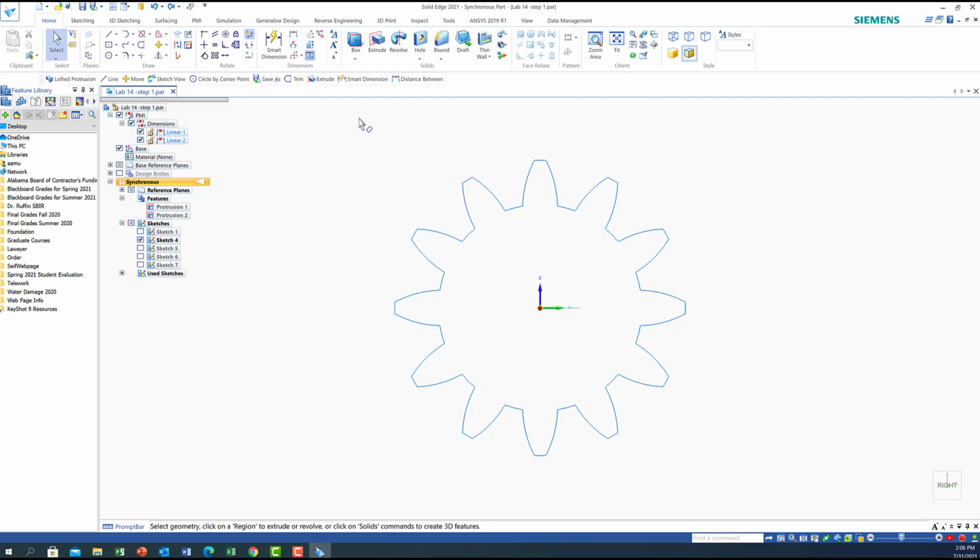So now what I'm gonna do, I'm gonna highlight the shape or the sketch, and then go to rotate and specify the step. I'm gonna use the whole step, which is 25. Okay, this is the helix angle. I'm gonna say enter, and then after that, make sure that you press the control key. So I'm gonna press the control key, and then come to this location so I can get the center. So I'm gonna highlight the center, click on the center, and draw a line, which I'm gonna use as an angle of rotation.